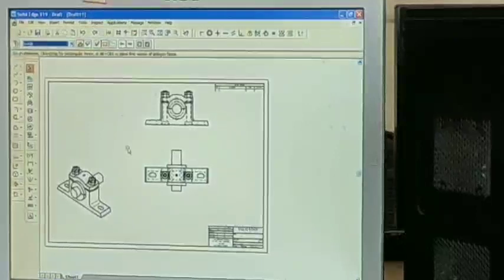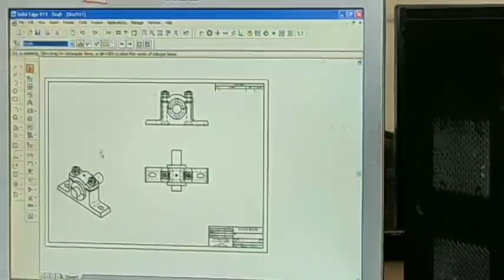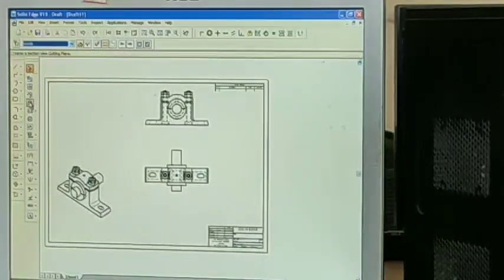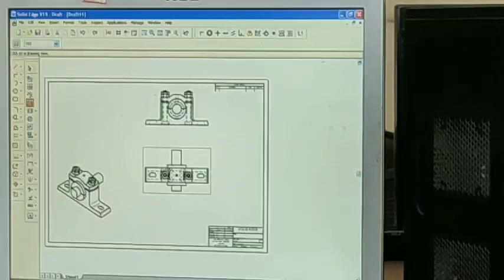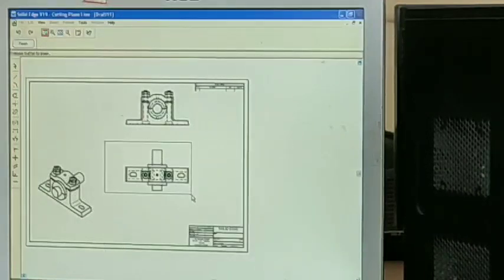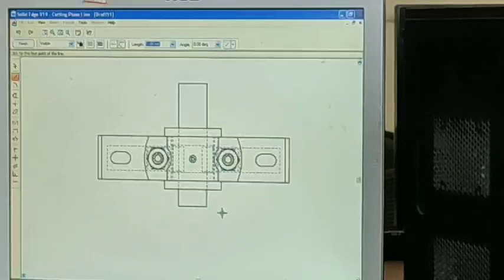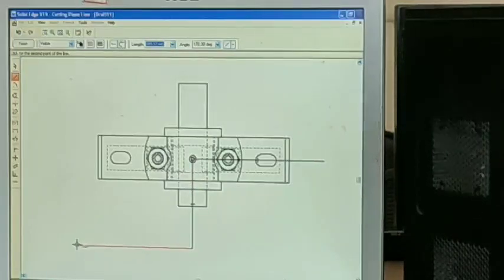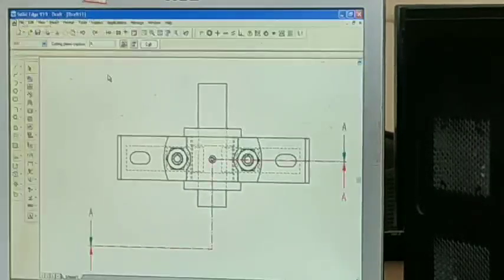Now I am going to do right half inch section. So for that one, take cutting plane, select this top plane, make a zoom here. So from this mid point, construct one horizontal line. Again with the same point, one vertical and one horizontal line. Finish.